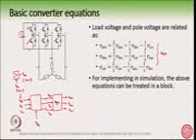So you have a very simple logic where, by getting the values of SA, SB, SC, with the help of the VDC, I can have the VAO, VBO and VCO. And how do I get SA, SB, SC?